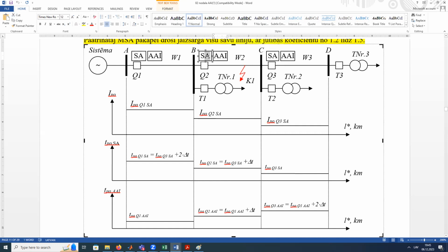So this current protection disconnected the line, we run a recloser, and for this time of reclosing, we'll disable the delay for a current protection. So in case if we connect this line back and there is a fault, this relay protection will disconnect this breaker immediately. Is it clear?